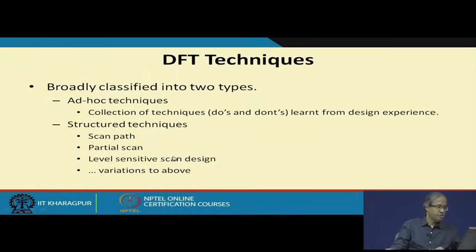So, talking about the DFT techniques, broadly they can be classified as either ad hoc or structured techniques. Now, ad hoc techniques, as the name implies, are really ad hoc. They are a collection of techniques, that means a long list of do's and don'ts. Some experienced designers have provided a list that you should not gate a clock, you should not do this, you should not do that.